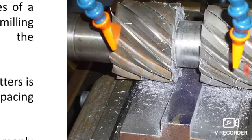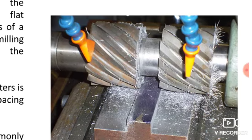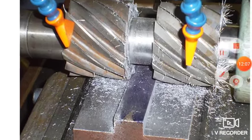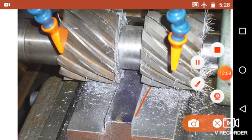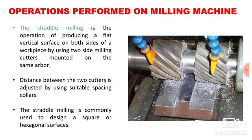So here you can see an image of straddle milling. On the arbor you can see two different cutters. The distance between the cutters can be changed with the help of a collar. So here these two different cutters are removing the material from the side. This is nothing but the side of the workpiece. These are two different sides of the workpiece, and the material is removed with the help of these two different milling cutters. This is known as a straddle milling cutter.